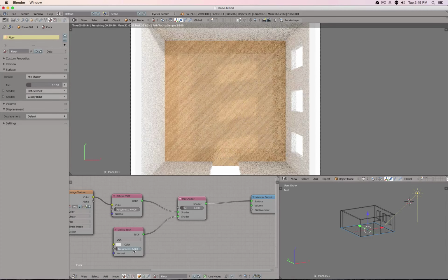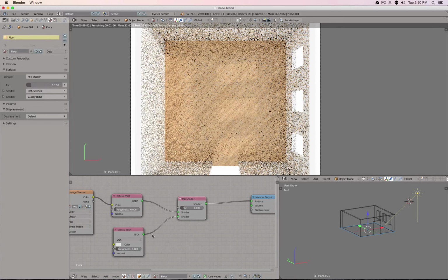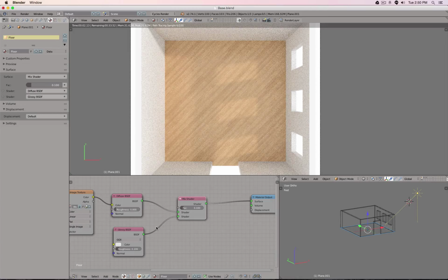And for example, let's set this roughness to 0, because that defines how smooth the reflection is. Now, the wood floor should not look like plastic, but more like wood, so it has a little bit of structure to it somewhere. It's not super polished. There's a little bit of shininess, but it's kind of blurry, so maybe 0.1 might help.